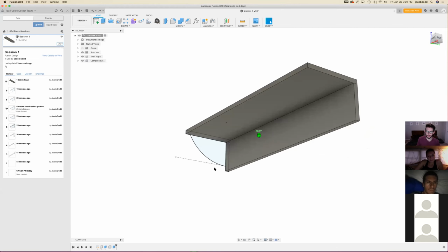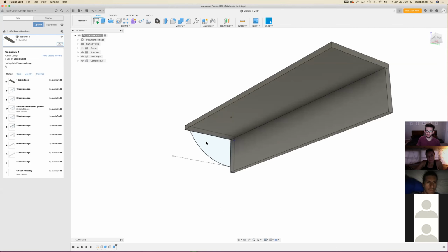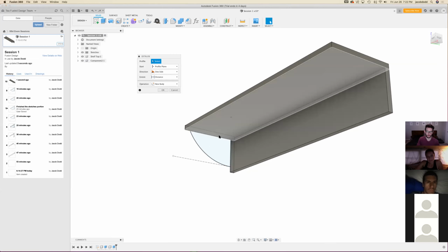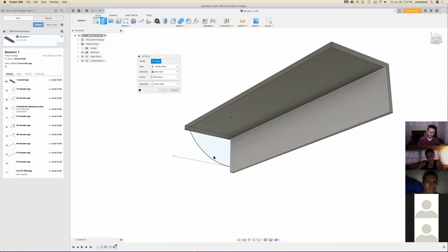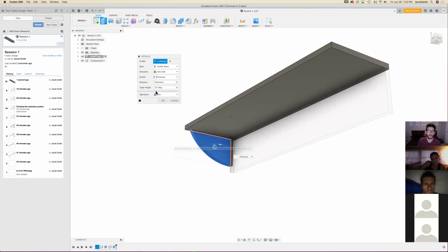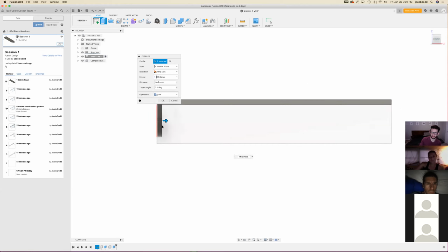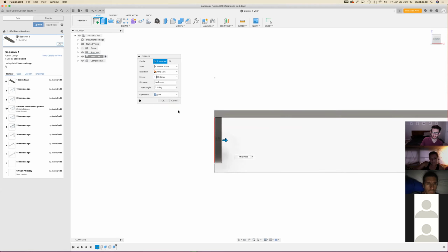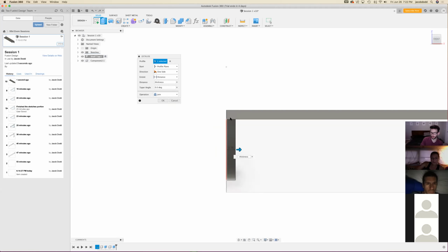So we will use Extrude again and select the profile for the shelf bracket. Yeah, and we'll say that's going to be extruded by thickness, because it's just going to be one thickness of width. And again, it tries to join them together. One of the things as well, if you remember, we said, if I look at it from the front, we don't want it to be right at the edge, because for a few reasons, it's not going to be as strong. You could split the end grain of the wood as you fasten it together, all the rest of it.